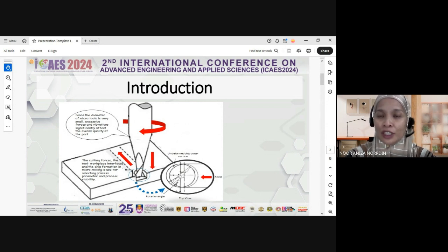Unlike macromachining, micromachining must take in essential factors of the cutting tool edge geometry, tool offset and run out, tool deflection, vibrations, material microstructure, thermal expansion, tool rigidity and stiffness. These factors completely change the interaction between tool and workpiece in micro scale, which makes the machining process considerably hard to pursue.